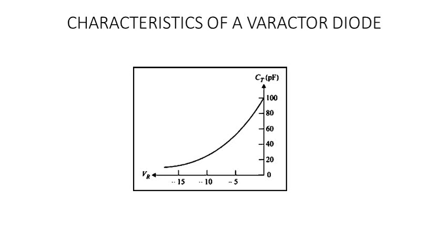So they are inversely proportional. The value of the reverse bias voltage should be below the breakdown voltage, because above this, the value of the capacitance equals 0 because of the breakdown of the depletion region and the free flow of holes and the electrons.